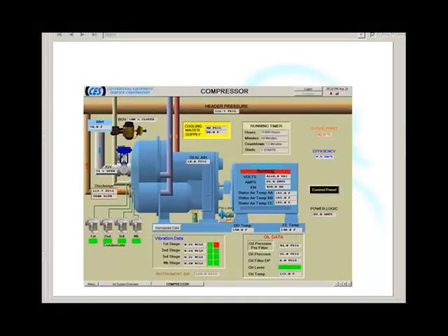Here's a typical compressor that's been put onto a PLC with a SCADA system. And this is what we're going to be doing increasingly. So it really is becoming part of instrumentation's territory. When we're setting this up, once again you set up the filtering to check for high and low limits. One reason why there's a push to computerize compressors is because it is just so very expensive to make compressed air. And if there's any way we can do this more efficiently, then we will.